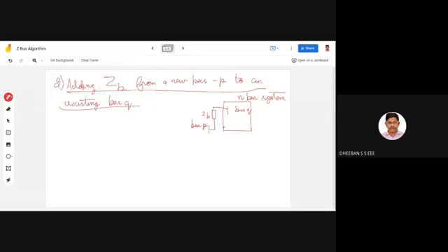So how your Z bus new matrix becomes is, it becomes in this fashion. The same thing goes with Z original. Okay. Now how the values become: this ZB gets added to your ZQQ. It is this element here, the ZQQ will be there, right? So the last point of this element gets added with this ZB, and then you have to write the same values Z1Q over here, then Z2Q followed by ZNQ.